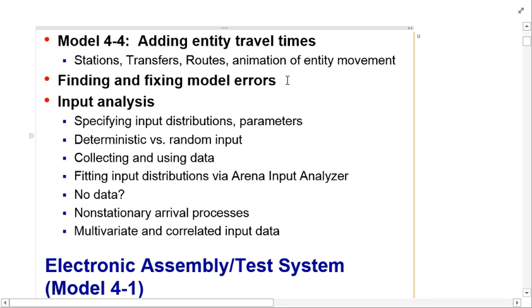The key point there, which I'll keep harping on, is keep your first iteration simple. With a simulation, get something that'll run. Similar to writing software code, keep it simple. Start with something you can get to run and then build on it. The other key point is save, and save often. If I'm starting with a fairly simple simulation and I need to expand it to make it useful, I save that simple simulation, then take that file and save it with a new file name or new revision.